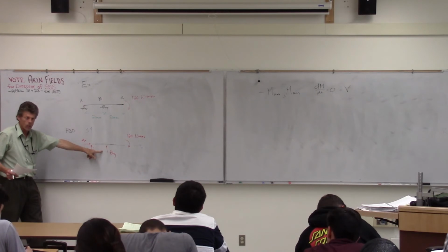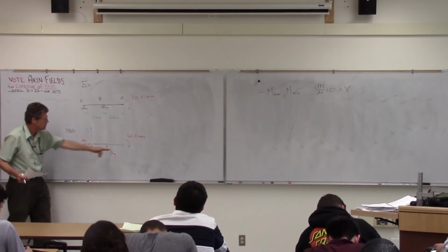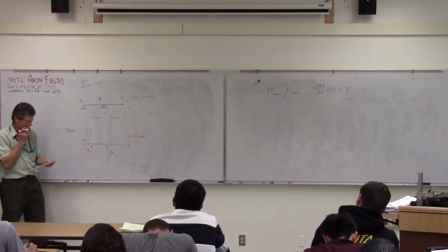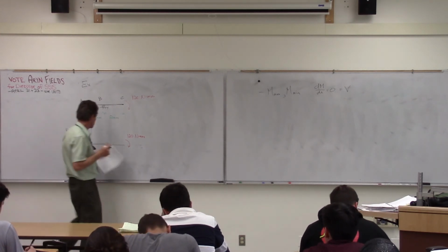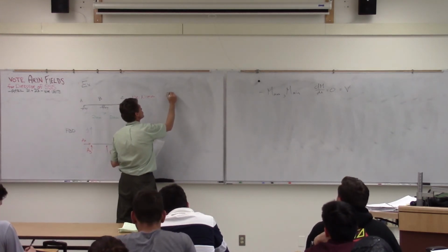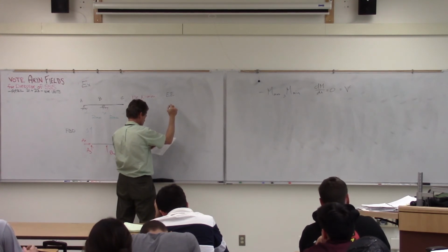It's an unknown force, unknown direction, so we substitute the two components of that particular force. B is a roller, so we already know its direction. It's only going to be in that direction. And then I got my concentrated couple at the end there. Now the first thing I need to do is start solving for those end forces. So we do my equilibrium equations.